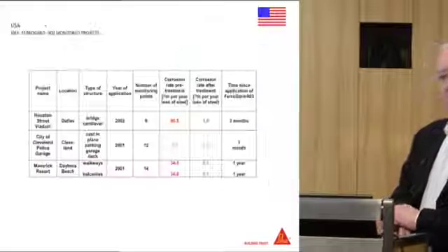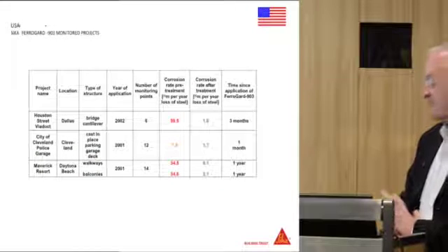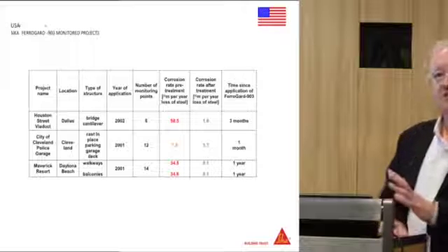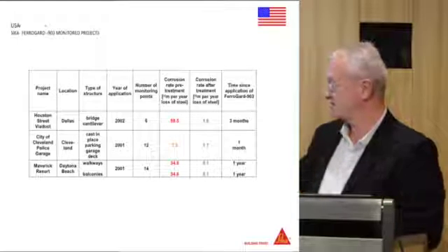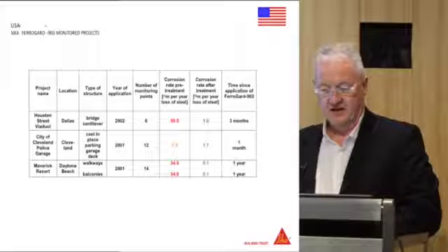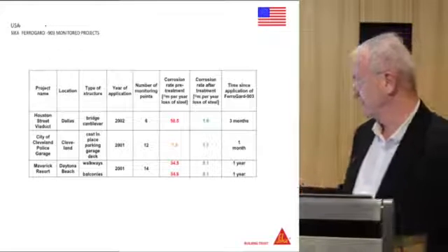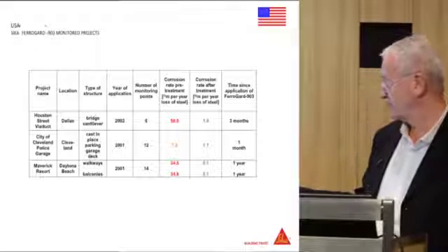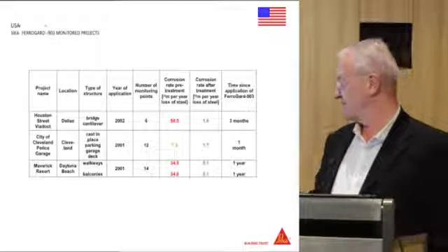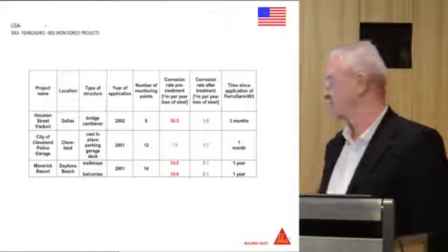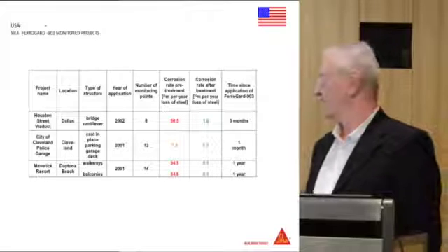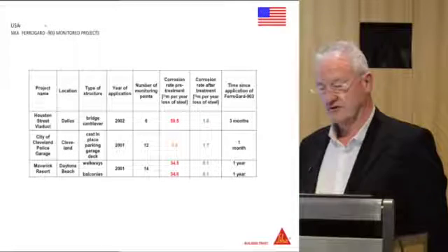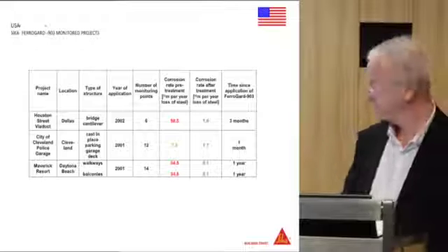In the States, they use the same product. Again, they just happen to use the same testing house with the same equipment to do some testing over there, and again, very similar results. You can see down from 50.5 to 1, 7.9 to 1.7, but nothing going to 0 with the use of the inhibitors. But again, controlling that corrosion on the reinforcement.